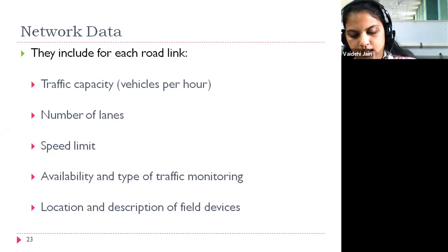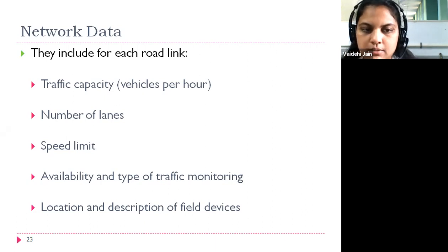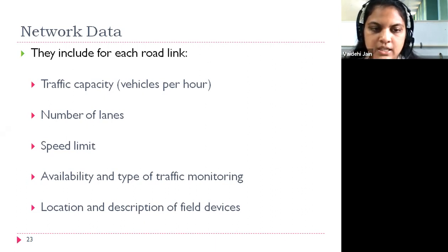The speeds are of very different types. We will not go much into that, but among those, we are selecting the operating speed. The operating speed is the continuous running speed of a vehicle. We are selecting that speed to decide the speed limit.